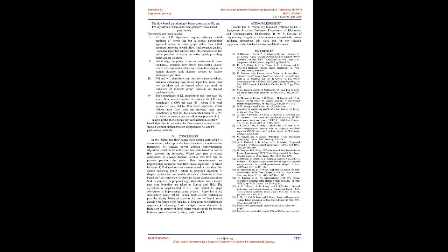V. Conclusion. In this paper, flow-based logic design partitioning is demonstrated, which provides a basic structure for the optimization framework of stacked power domain implementation. The algorithm partitions the netlist into 2 parts based on the current flow between the instances, where each part or cluster corresponds to a power domain. An iterative max flow min cut process partitions the netlist. A few improvements are implemented compared to the base flow-based algorithm. 1. V-shaped vertices were removed in the base algorithm during the clustering phase, whereas in the proposed algorithm V-shaped vertices are not considered; instead, clustering is done based on flow difference.